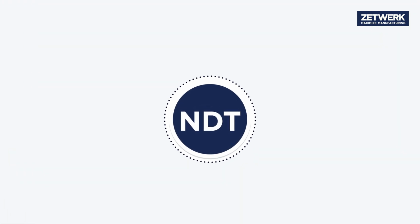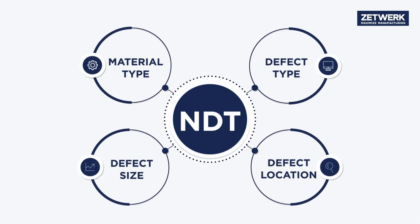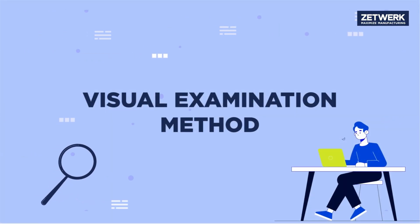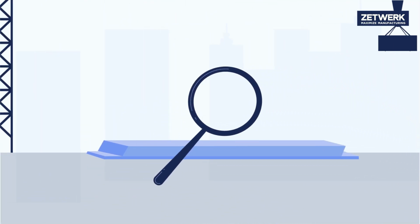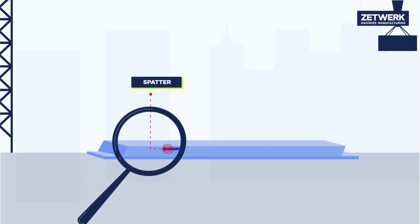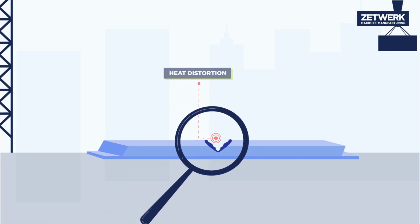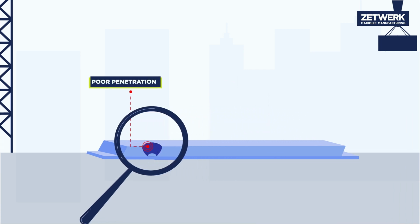There are various NDT techniques that stem from the main criteria of material type, defect size, and defect location. Let's begin with the visual examination method. The visual examination technique is often the first step in the NDT process. It looks at surface defects like spatter, excessive buildup, heat distortion, undercutting, and poor penetration to help decide the level of acceptability of the material used.